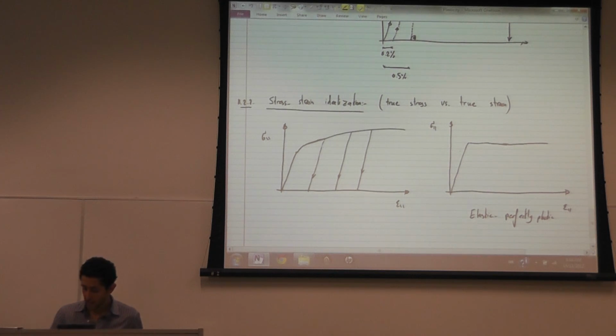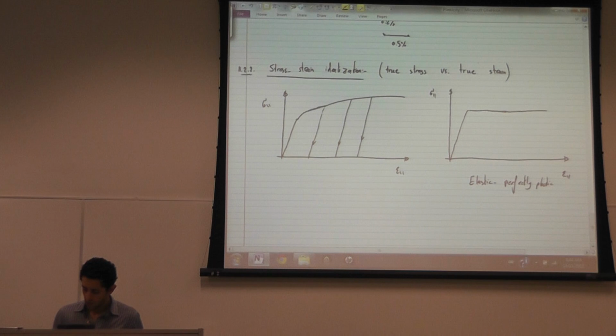So when you have a plastic hinge, and you apply a moment, you assume that the stress never increases. So you assume this kind of behavior, if you've ever seen this before. This is a beam, you have your tension, you've got compression, and you assume that it would be much easier to assume that this is perfect. In reality, the stress level increases.